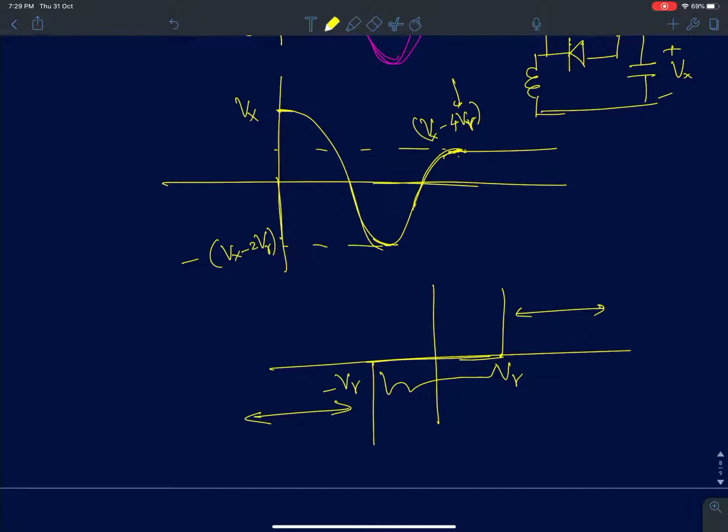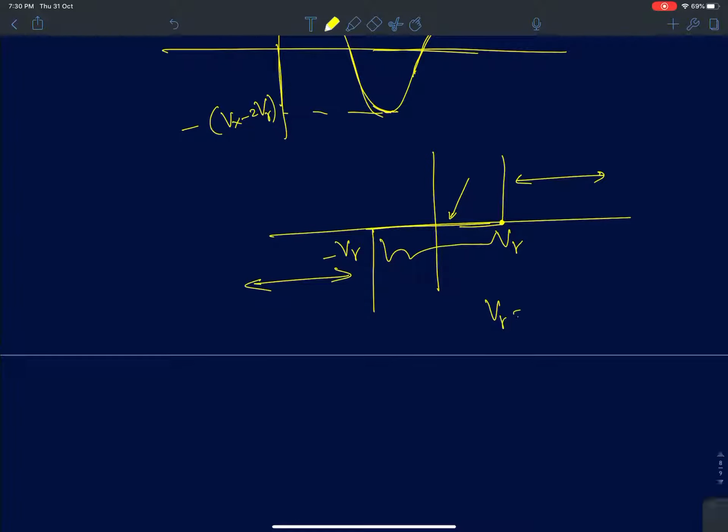So finally the capacitor voltage will settle to a value between minus V gamma and plus V gamma. In one special case, we assumed V gamma as 0.5 volts, and it directly came to 0, which also lies comfortably within this range.